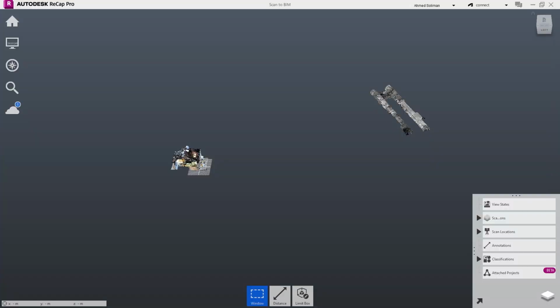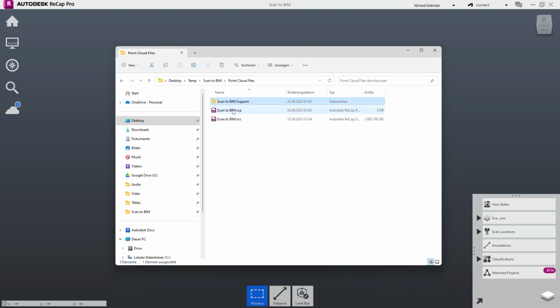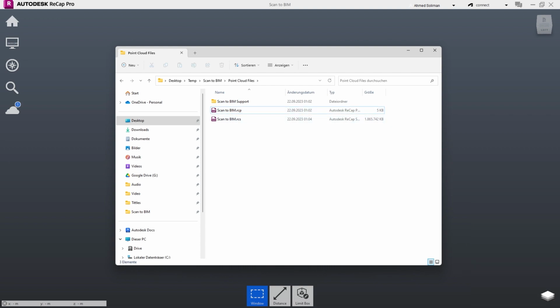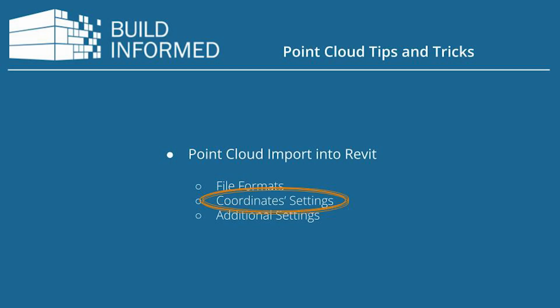Even though the size of the two options don't differ drastically, it's a good idea to use RCS files as they are easier to move around from one location to the other, hence providing more flexibility when linking files and dealing with visibility options.